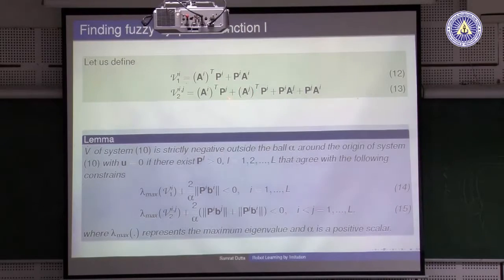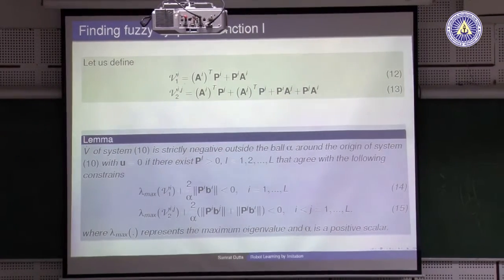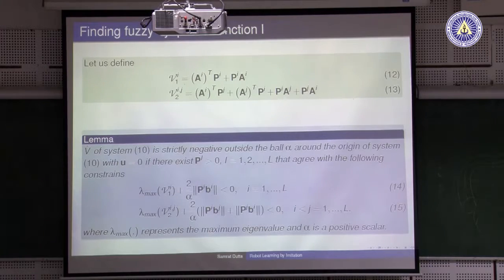right. That is coming from the Lyapunov function analysis that I have already shown here using x dot equal to A x. When we find P in this way, where this condition is satisfied, you can say we have found the natural Lyapunov function of the system, because we are learning the system from the data, right, because this B and A we have learnt from data. Now, this P we are also learning using this model. That means we are learning the natural Lyapunov function of the system. Now, using that, the controller U will create quite less force to distort it from the expected trajectory, right.